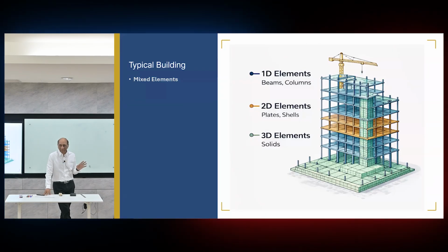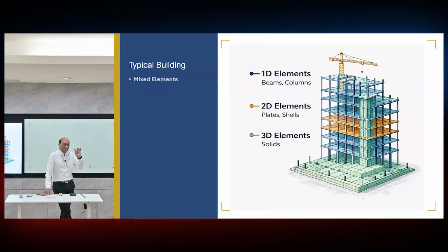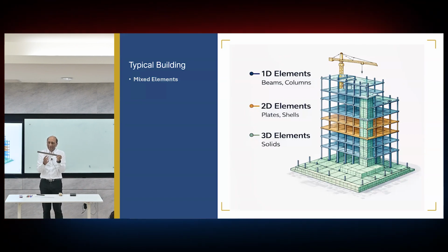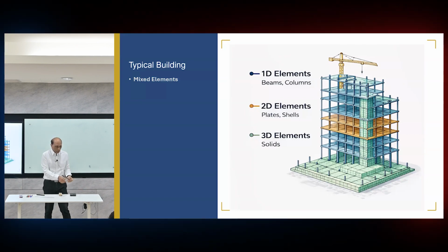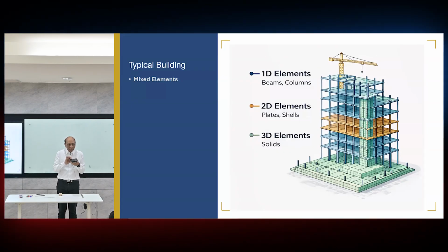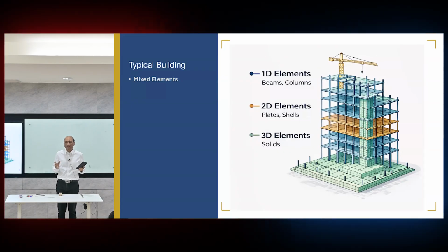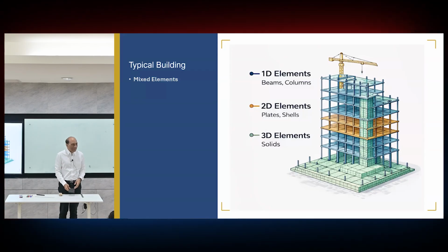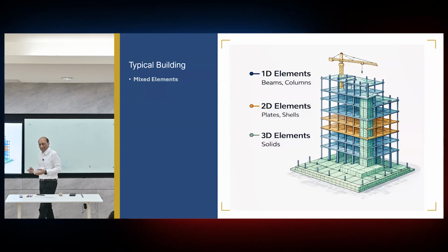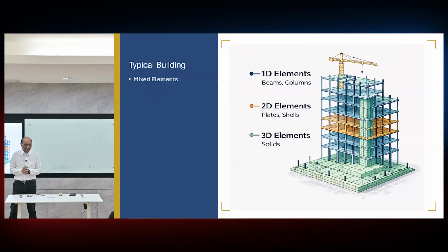Structure is always 3D generally, but the element representation is either 1D, that means only one dimension is modeled, the other two are properties. 2D means that two dimensions are modeled, third one is a property. 3D means all three dimensions are modeled, there is no property. So when you use solid element, it has no property. No moment of inertia, no thickness, nothing like that.